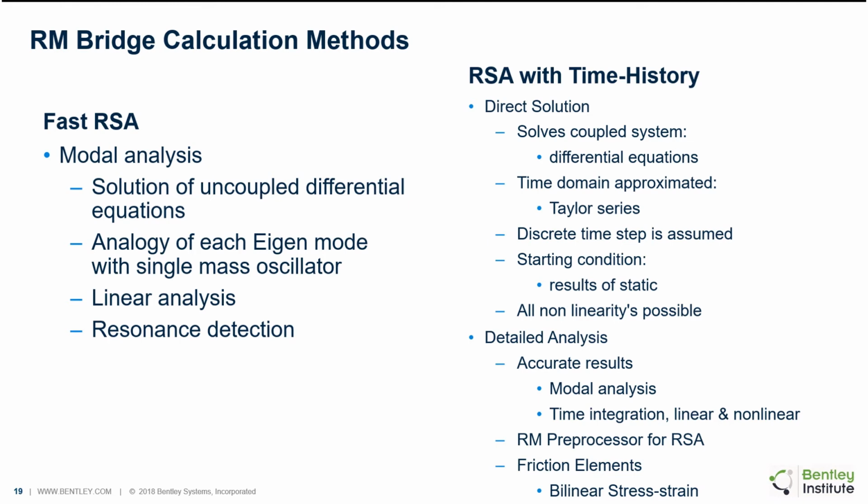So, what we can do is create our bridge as we did, run the fast rolling stock, and if it's fine, then just double check the design with the time history methodology without much changing of input. But if it doesn't work, for example, on all that criteria that I mentioned, right? Comfort of the passenger, maximum accelerations of the deck, displacements, and the frequency, right? If we check it using the fast rolling stock and it doesn't pass, then I have to stop my design and come back and redesign the bridge, right? Without wasting further time doing the time history analysis.